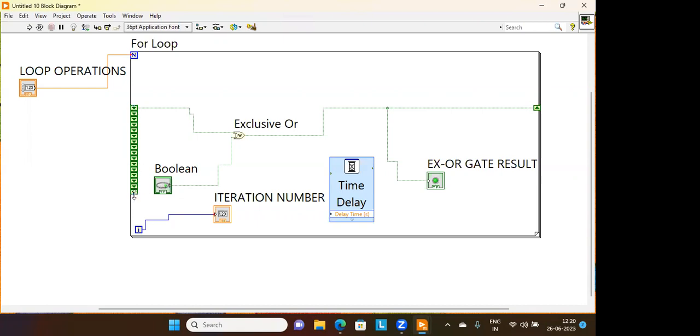Actually, how have I done it? This is the shift register. Move your cursor over there. Automatically, it changes to an expansion mode, and I can drag and drop it. Now, suppose I make it 2 shift registers. I know that in my first iteration, the output value is going to be 0. So 0 is being transmitted. But if in the second iteration I want to do something else with whatever output is there, then you can have a different logic. There is another wire from here, and you can connect it to some different logic.